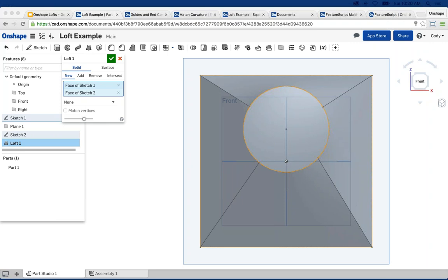Although I know, okay, so I'm making lofts similar to elliptical shapes, but the lofts make a knife edge in places. Although I need the knife edge to be thicker in order to 3D print it probably. Do you have any suggestions for preventing the loft from creating knife edges between faces? I will say there are two techniques if you're trying to create very slim profiles for lofts, and one is lofting to a point, which you can do. In the case of surface lofts, you can create a loft to a point, for example. And you can also thicken.